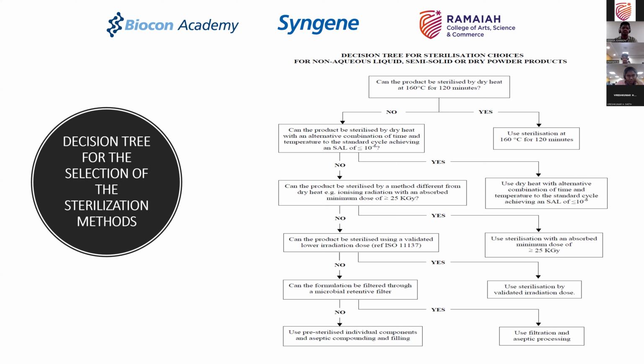So the only way to do it is to use a combination of aseptic processing and filtration techniques, where at certain initial stages we filter, combine it into the stage where the powder gets precipitated or a microsphere gets formed, and then you have to subject it to filtration technique using one of the kinds of equipment that I spoke about, and then fill it as a powder into the final vial.